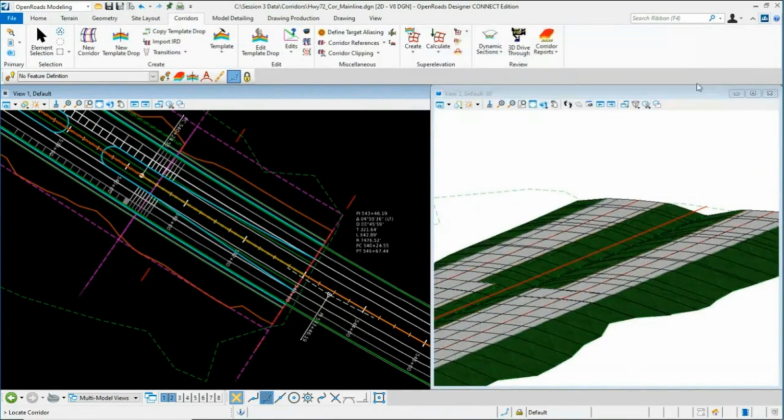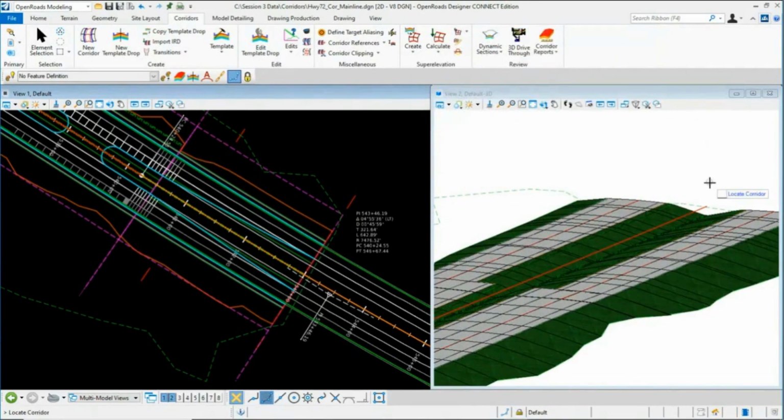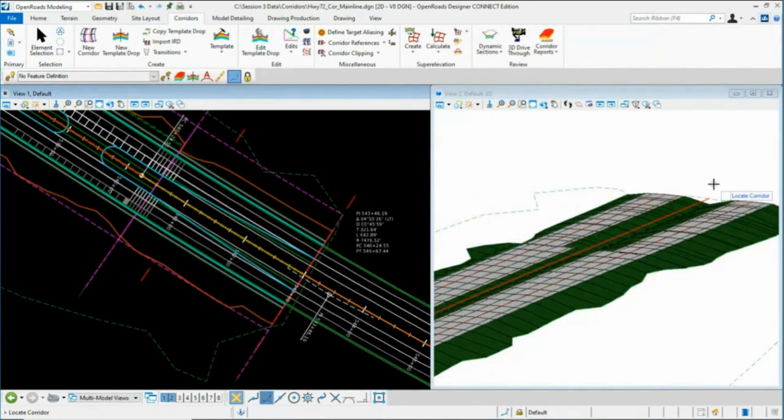So we're good there. We're about halfway there, right? There's still some things we need to take care of. We need to address our super elevation. We need to address the separate profiles, or the separate vertical alignments, those transitional vertical alignments that we have at the beginning and end of the project to get it back to grade. We also need to address these tapers.